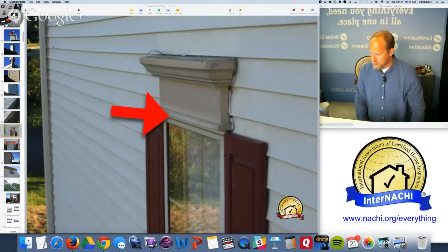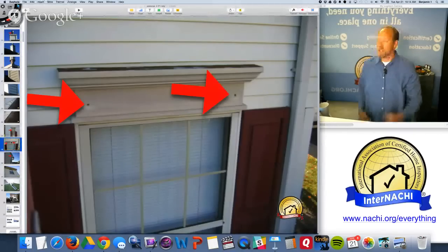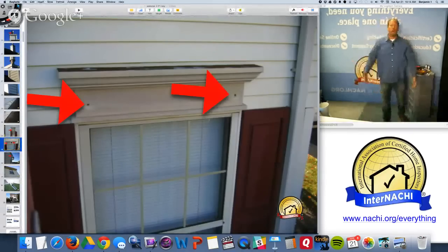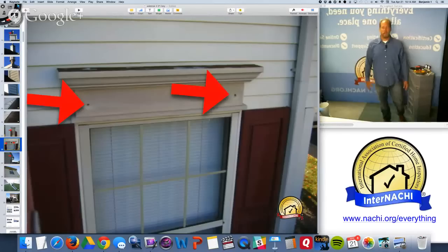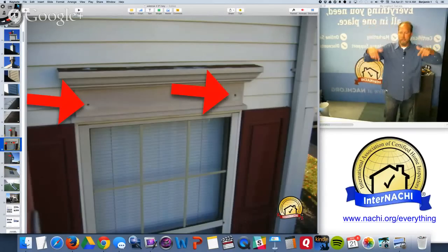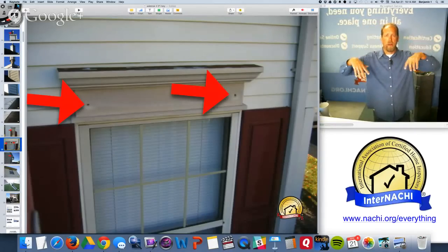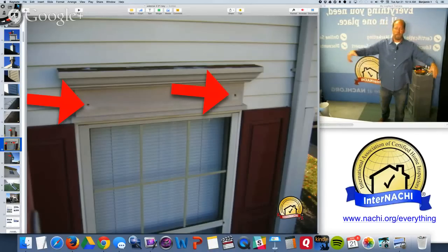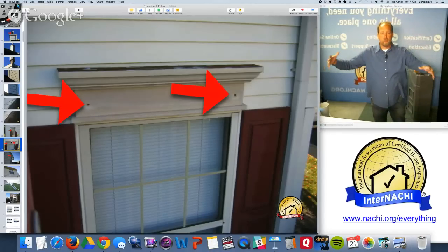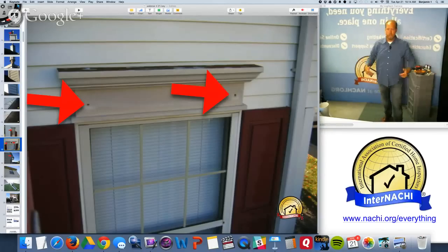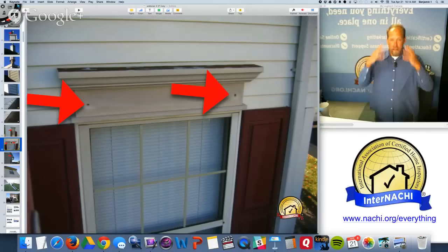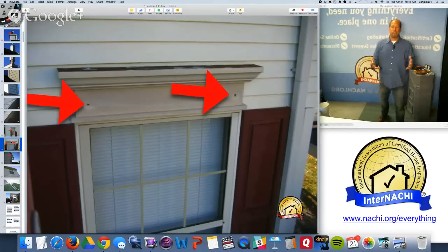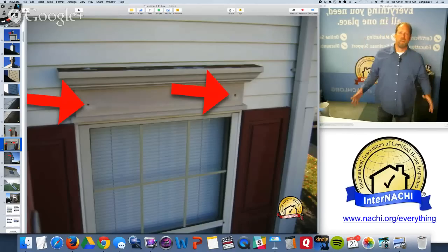So as I'm going through the systems, I start with the roof, and I'm thinking of how water is shed off of this structure. It starts with the top. This house is in Pennsylvania, so there's a lot of rain. I'm following the slope of the roof covering, thinking of how water is controlled. It's caught by some gutters, some downspouts, but I'm also looking at the siding as well. I have to think how water moves around. If I keep that in my mind, it actually guides my inspection. My visual inspection is guided by how I think water moves off of the structure of the house.